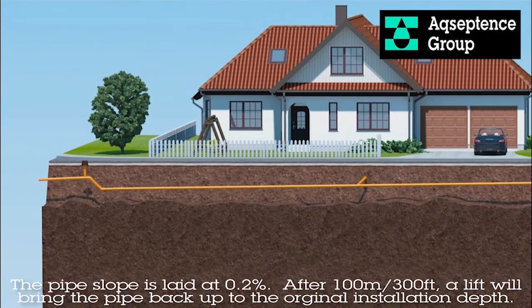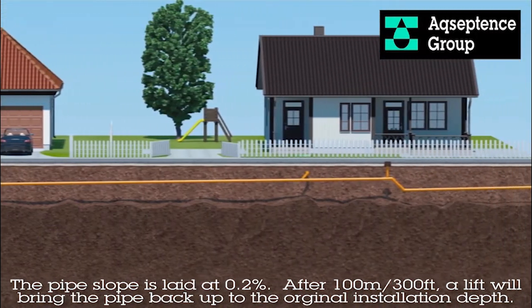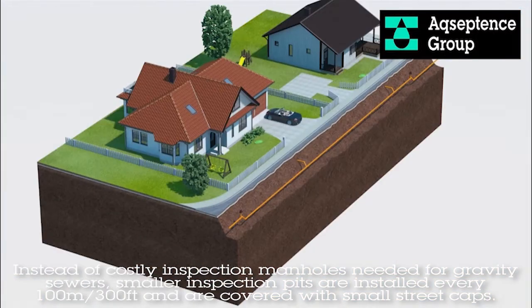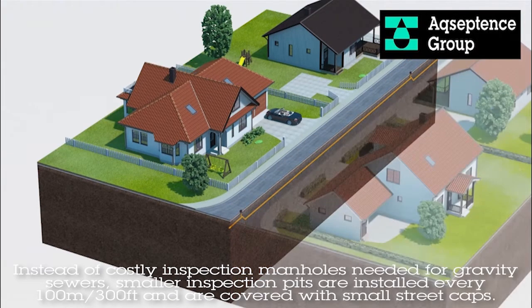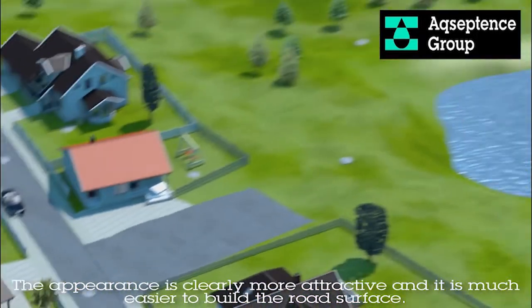The pipe slope is laid at 0.2%. After 100 meter or 300 foot, a lift will bring the pipe back up to the original installation depth. Instead of costly inspection manholes needed for gravity sewers, smaller inspection pits are installed every 100 meter or 300 foot and are covered with small street caps. The appearance is clearly more attractive and it is much easier to build the road surface.